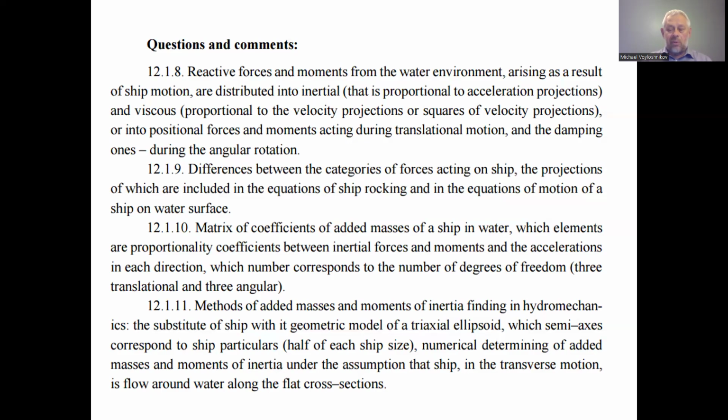Some of the added masses are not masses, some of the added masses are moments of inertia. And some of the added masses are just some concept intermediate between the mass and the moment of inertia, a characteristic of the inertia of the water with the ship. It depends on what direction we consider. Is it the translational direction? That is the added mass. And the angular direction, this is the added moment of inertia. But there could be just something in between.